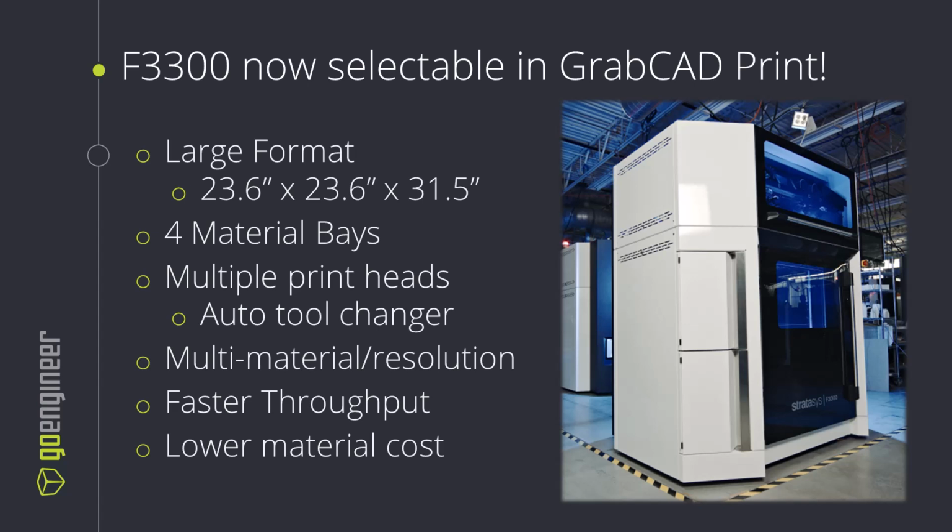Because it holds these 4 materials and each is using a different print head, we can print multiple materials at the same time and have multiple resolutions or Z-layer heights. We're going to have a faster throughput with faster servo motors and gantries, and a lower material cost as the material comes on open spools rather than canisters. They're loaded into dry chambers, so the print quality is kept up the entire time. Be sure to check out this machine and let us know if you have any questions about it.